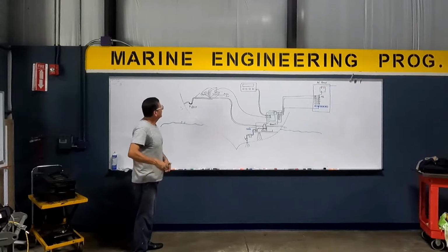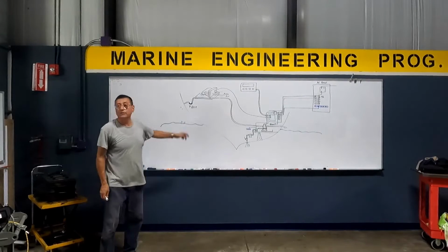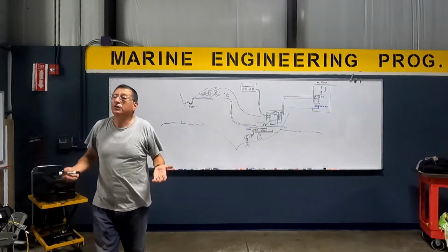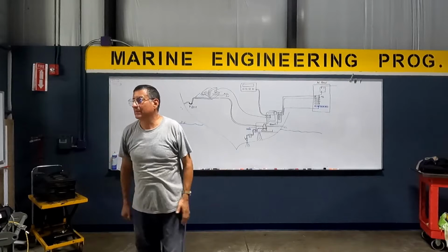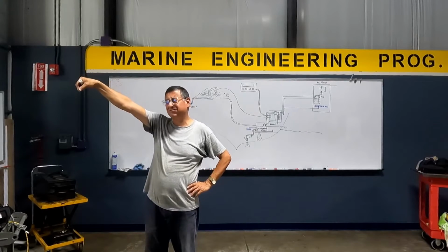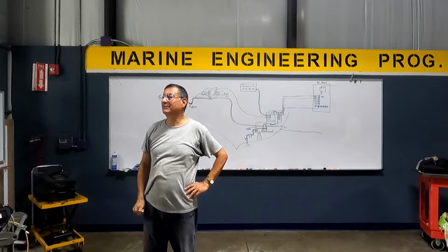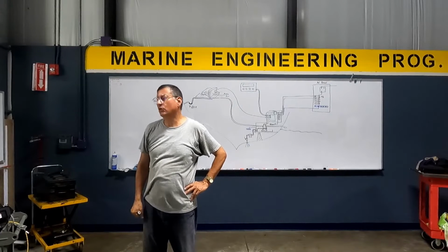So if you had a lack of airflow, so if you had airflow but not as much as you should, it's because that coil is dirty. It's because the coil is clogged with dirt. Or the air filter. Oh, look at that air filter. That's the problem. So I have a problem in my house. Air filter is clean, but I looked yesterday and it's all clogged. Correct. So I gotta clean it.